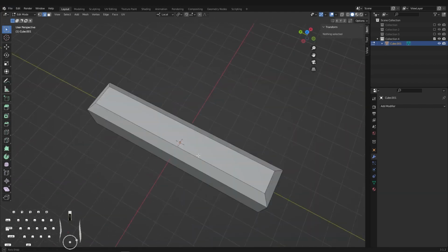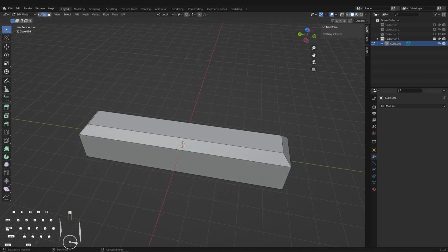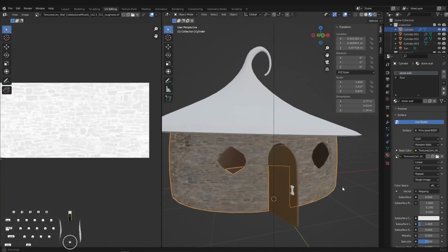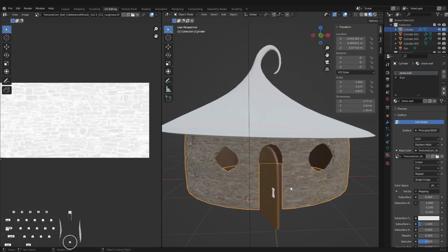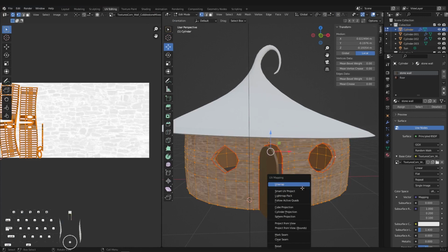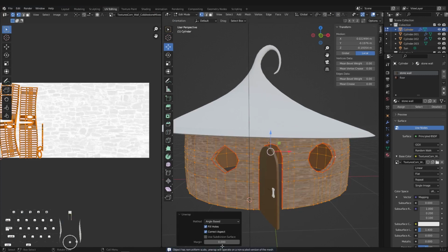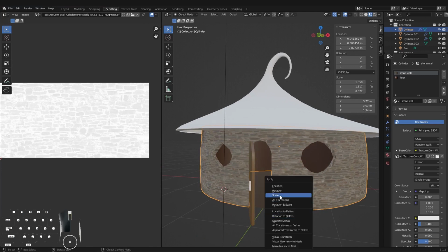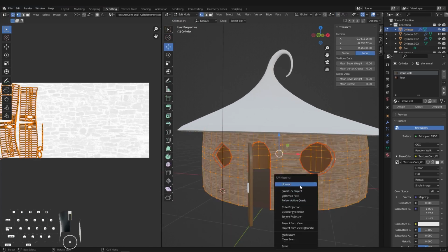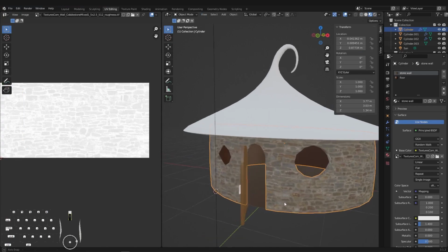Another time this causes an issue is with UV unwrapping. When you're texturing, if you haven't applied the transforms, your UV unwrapping can also turn out pretty whack, like with things stretching weirdly and stuff. So remember to do that before you try to unwrap your objects. You'll get a warning at the bottom about the object having a non-uniform scale. You see here is without the transforms applied, and then here is with them applied. You can see the weird stretching is fixed.